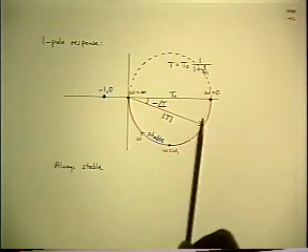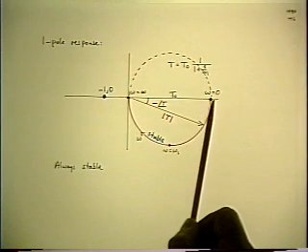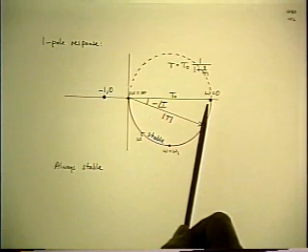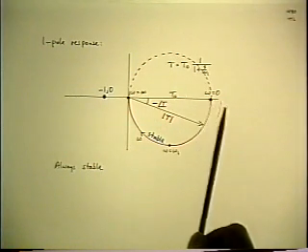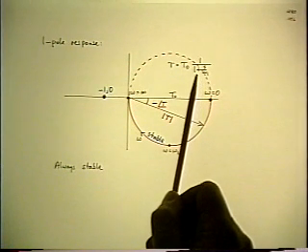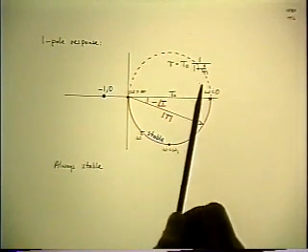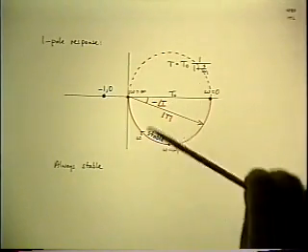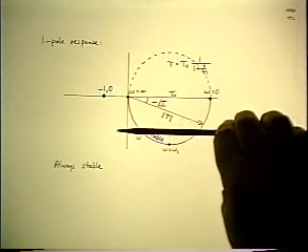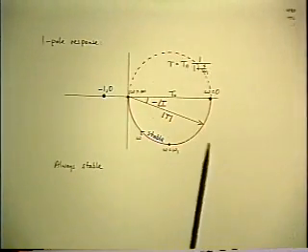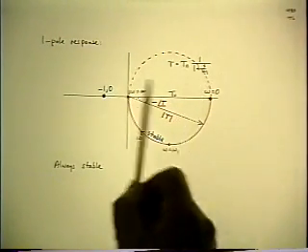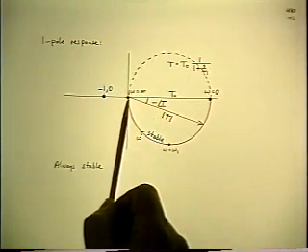Now, Nyquist said we have to draw the contour not only from frequency 0 to infinity, but also from minus infinity to 0. And that's easy, because the only difference is the phase angle is reversed for negative frequencies. The magnitude stays the same. So the negative frequency contour is simply the vertical inversion of the positive frequency shape, and since that was a semicircle, the full contour is a full circle. In this case, the negative frequencies, of course, is what closes it.